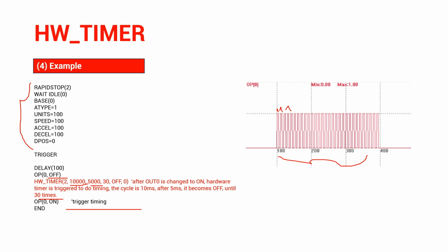At last, we see the waveform. 30 outputs, and the interval of each output is even. Here, the duty cycle is set as 1 to 1. If we set a bigger valid level, the output in the waveform will be wider. And the total time is the time of each cycle multiplied by the total comparison times.